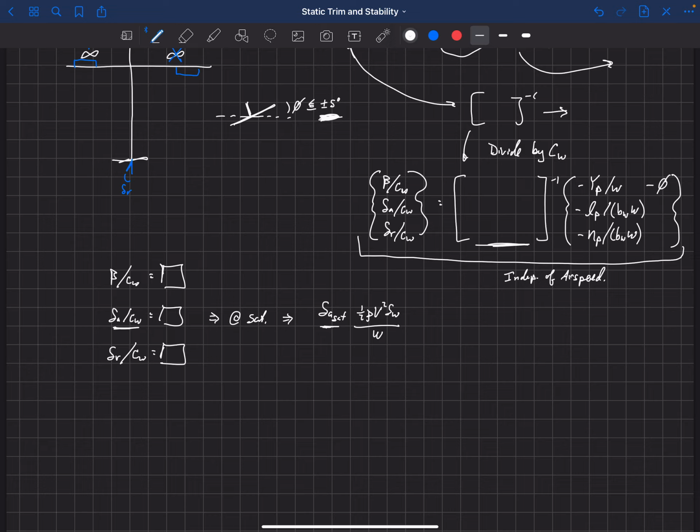And the velocity associated with that saturation, I'm going to call that my minimum control airspeed. So at the point where that saturates, that's our minimum control airspeed, okay? And this is equal to the value that I got over there from this. I'm just going to put an arrow here. This is equal to that delta A over CW that I computed from this expression up here, okay?